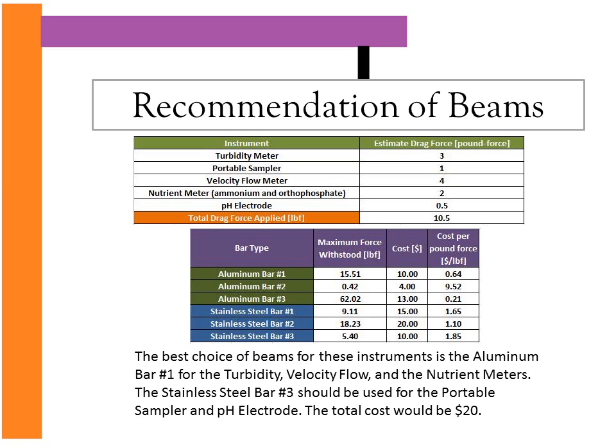Since we wanted the least possible deflection, we decided to make the thickness greater than the width whenever possible. Although the width was directly related to stiffness, it only had a value of +1 in the exponent. For this reason, an increase in thickness would have a much greater impact on the stiffness of the beam than an equal increase in width.